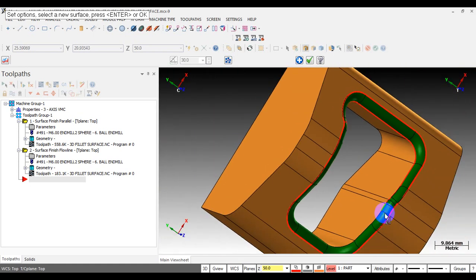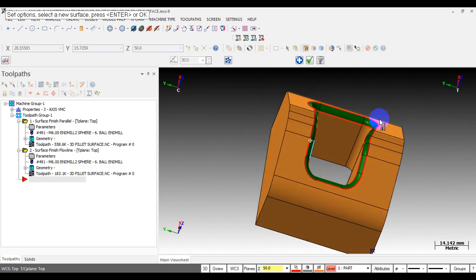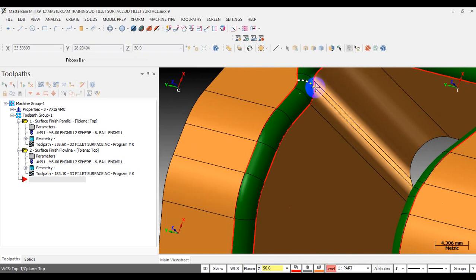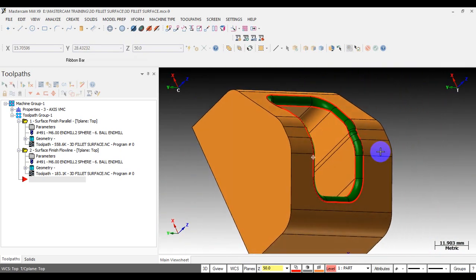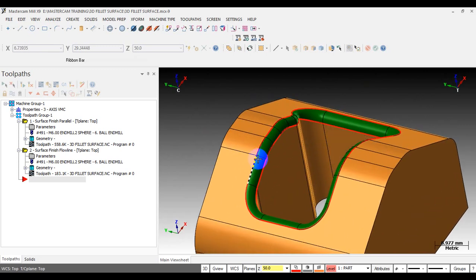Okay, we are done. I will erase this curve. So you've got all you need for a plane toolpath. You have the surface to machine in green color here, and you have two curves, one outside and one inside, that will guide the tool.